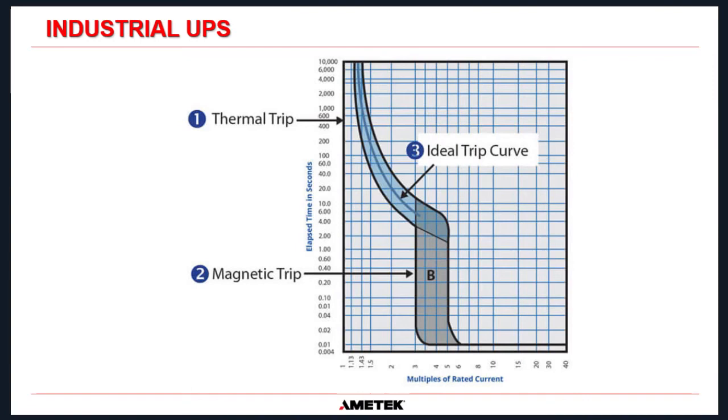So that's why it's very important when you are designing a UPS. If the existing UPS that you have there is an old commercial UPS and it uses a 208 volt output, consider changing the AC panel to a single phase. Consider changing the UPS to a single phase, because you will find that all of the loads that UPS supplies are single phase. Okay, so that's the first common misconception. It is much better to have a single phase UPS connected to your 120 loads, without a doubt.